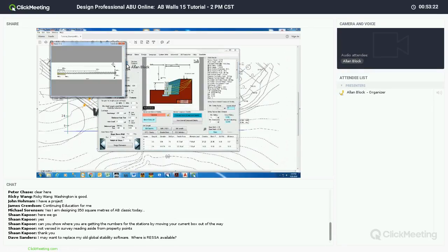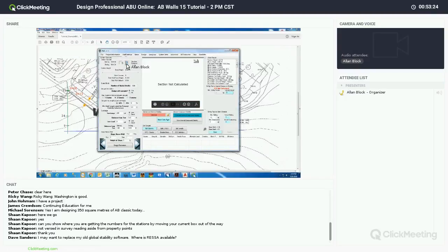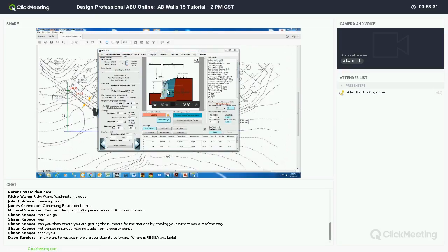I'm going to use the little blue arrows to go down to the next sections. Section 5, I'm going to hit match grids right now because I'm on the other side of my starting section. And now if you notice, the first layer of grid starts on the second course of block. That is acceptable based on 2 course spacing and with best practices, so this is a good design. All right, now calculate internal compound stability.